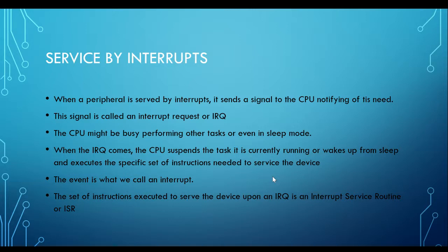be interrupted. Okay, you get up from your sleep mode and then the computer does something. When the interrupt request comes, the CPU suspends the task that is currently running, wakes up from the sleep in the case of sleep mode, executes the specific set of instructions, and then probably you go back to sleep mode, or you go back to the main program. This event is what we call interrupt.